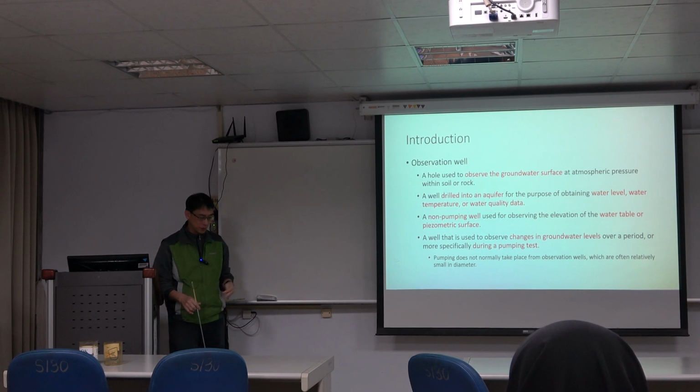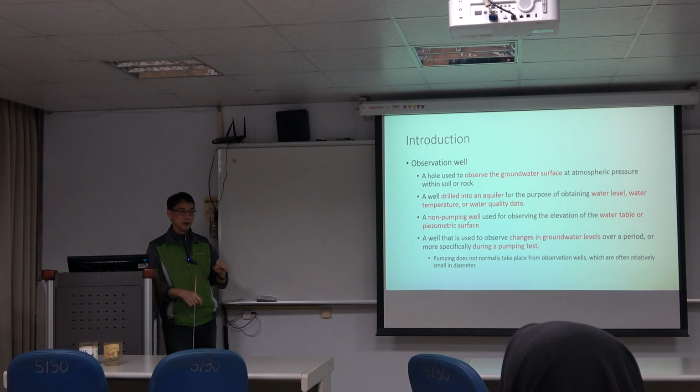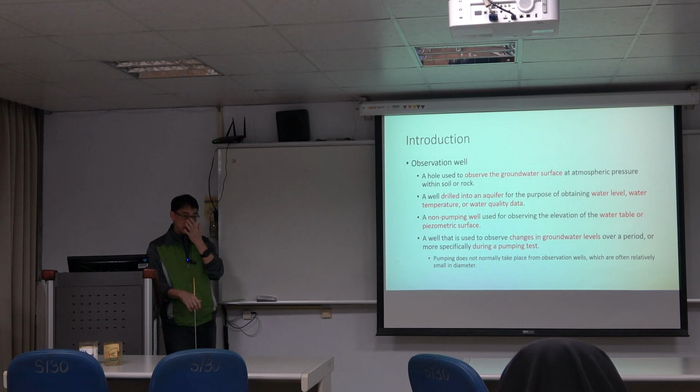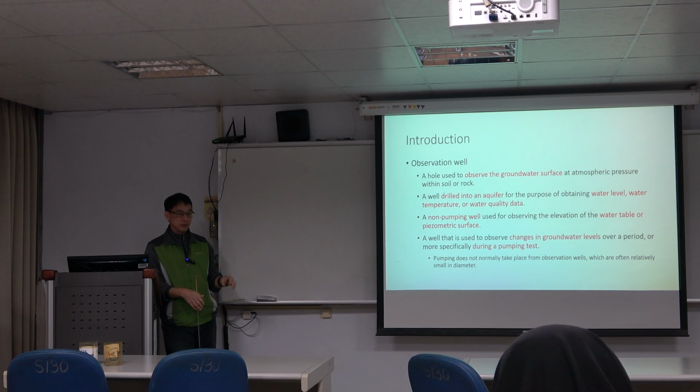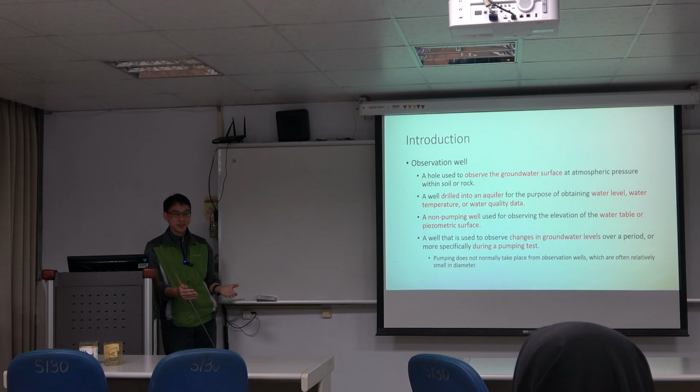That's also a very important part, because 2 years ago I evaluated a project. I gave comments on a project. They drilled the boreholes very near the rivers. They wanted to assess what we call hyporheic waters. And they drilled maybe just 2-inch boreholes because they imagined, oh, we just want to measure, we are just using observation wells. So they used 2-inch boreholes, and after that they did a pumping test. And the one problem is that their water level did not decline.